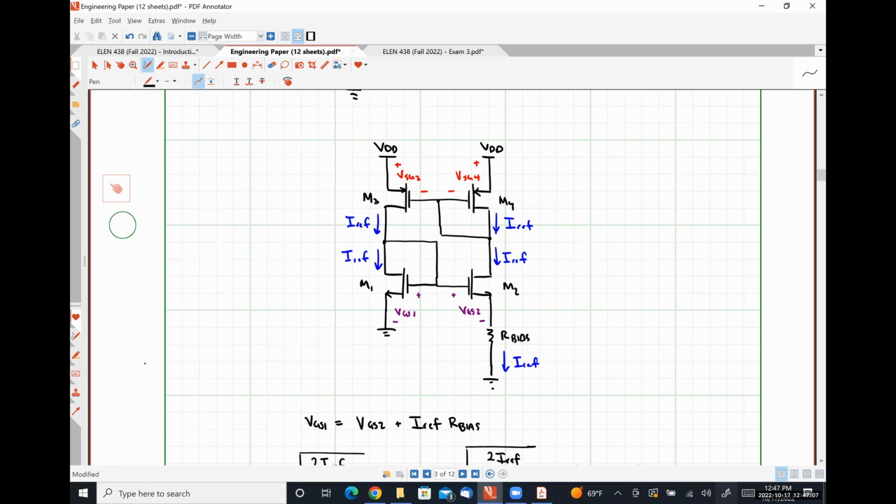It's stable if the loop gain is less than 1, which requires the value of R bias to be not small. What I mean by that is that if we accidentally shorted this thing out, at particular frequencies we are going to find that this could be problematic, as the internal capacitance of our MOSFETs will short this thing to ground, and we have an astable, or unstable, system, which is bad.